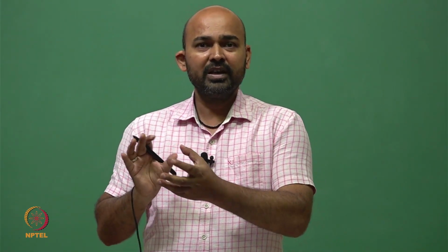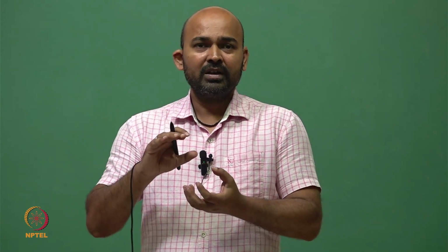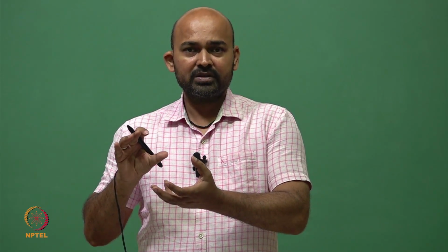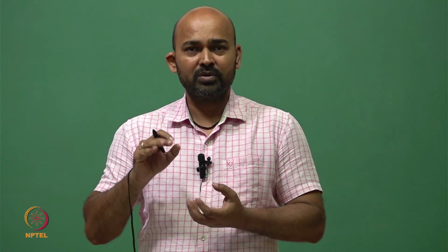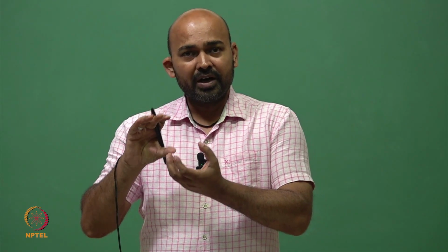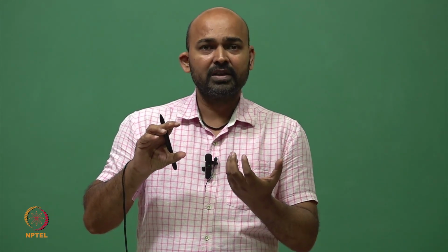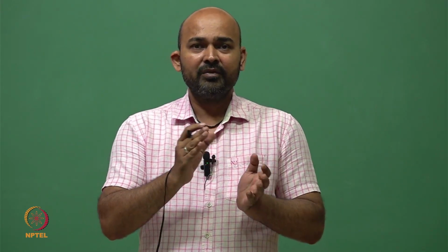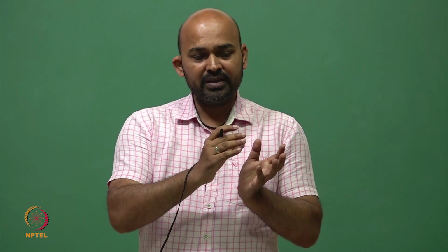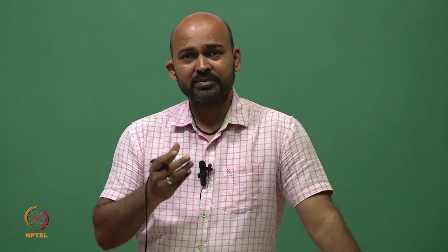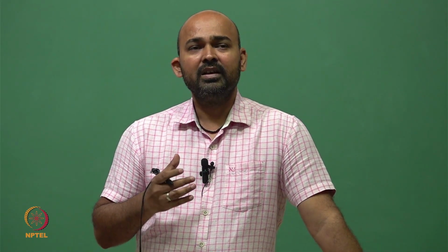This motor, however, is running at 250 volt or even beyond, and there is a spike of voltage because of this sudden shutdown of the motor. It can go up to thousands of volts. Now this high voltage has some parasitic capacitance connected to the input side, and this high voltage will easily influence the output of this microcontroller. So this parasitic capacitance or parasitic inductance is always there in electrical circuits.